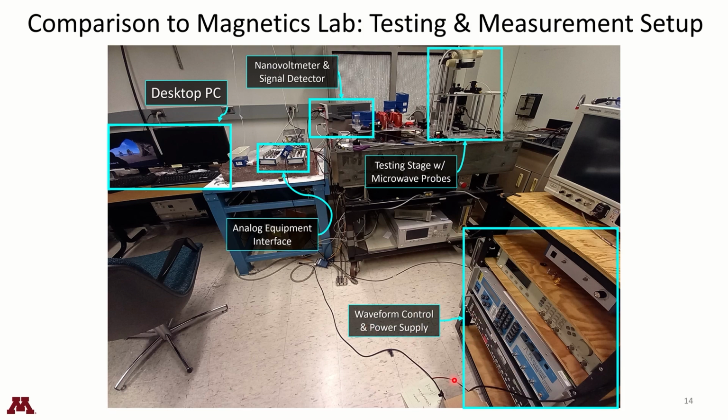And so this is where the high frequency signals are coming from at the gigahertz range. And then if you want to modulate or modify that signal, the waveforms, then it needs to be plugged into these other components here. And then from there you can plug it into the testing stage where the chip is ultimately located. So you can place a quantum chip here, a nanomagnetic chip here, some other chip that uses microwave frequency, and then you can use that microwave frequency to test or excite or stimulate that quantum chip, the physical device, and then that device will send a response signal in the end.